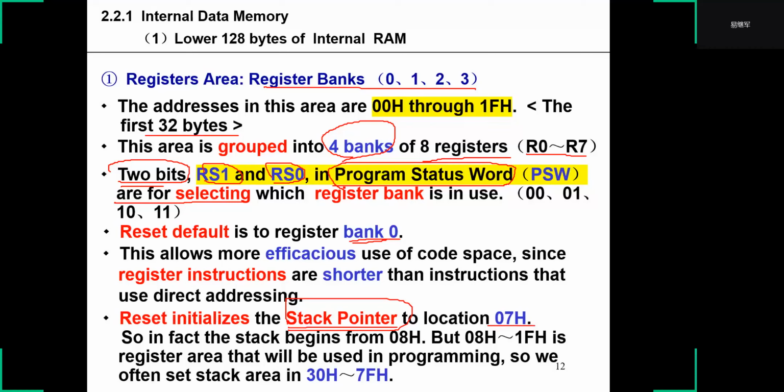So in fact, the stack begins from 08H. But 08H to 1FH is the register area that will be used in programs, bank 0 to bank 3.